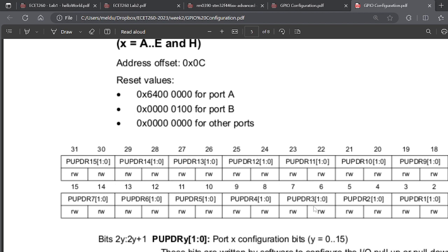So if you had need for a pull up resistor to make sure that some chip that you had was enabled or disabled when you first fired up, when you first initialized things, you can put that in without having to have those extra bits. You can individually on most pins set those up. And again, to keep it there, we have either 00, 01, or 10. 11 is don't do that. Who knows what it'll do?